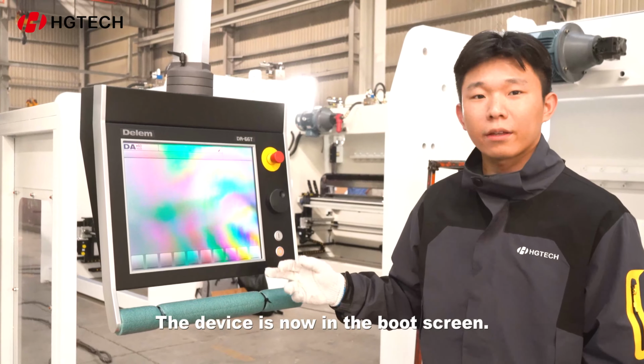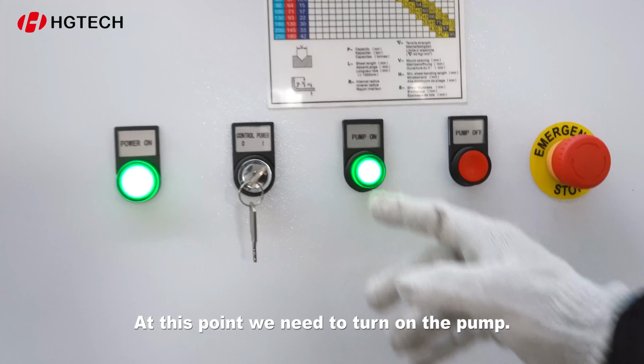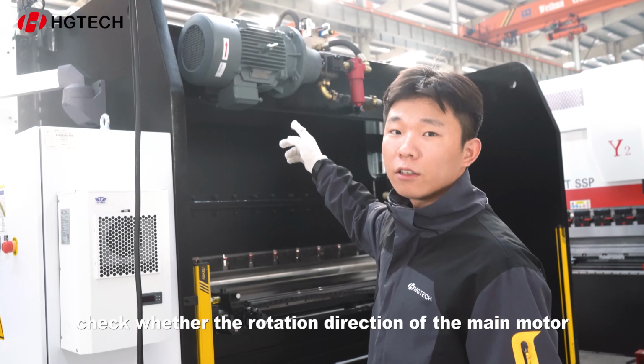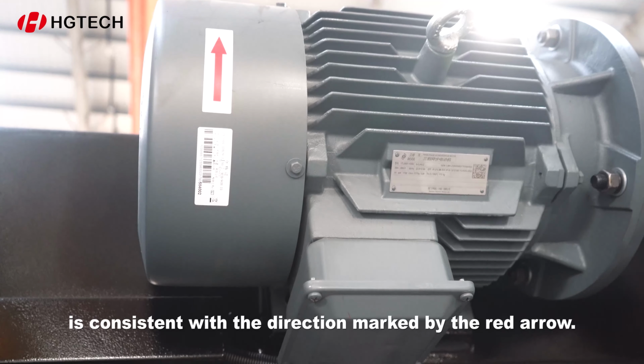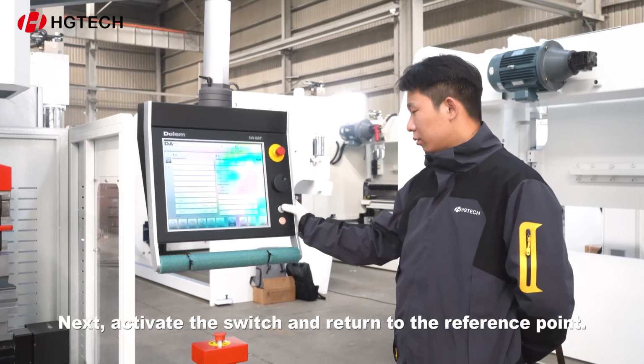The device is now in the boot screen. At this point we need to turn on the pump. When the oil pump light is on, check whether the rotation direction of the main motor is consistent with the direction marked by the red arrow. Next, activate the switch and return to the reference point.